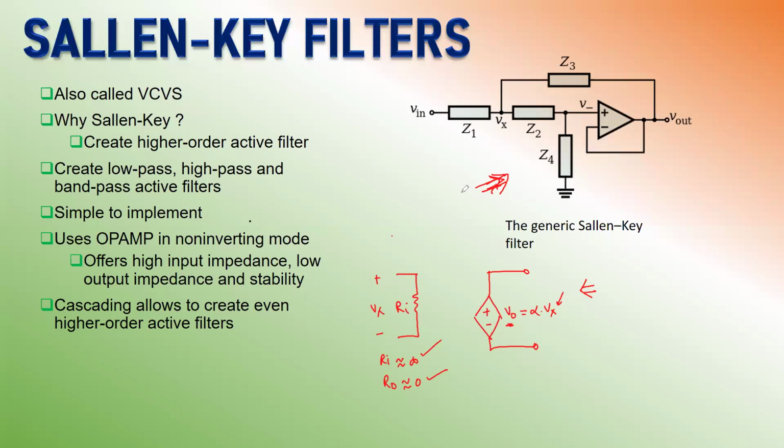So as you can see, this is your configuration, and you have used the difference amplifier with an extremely high open loop gain A, and you configured this block in a buffer stage in a non-inverting mode, used as a voltage follower. So the output voltage is equal to the input voltage VID, right? So we'll see why we use it as a buffer amplifier, because we have got these two advantages right here.